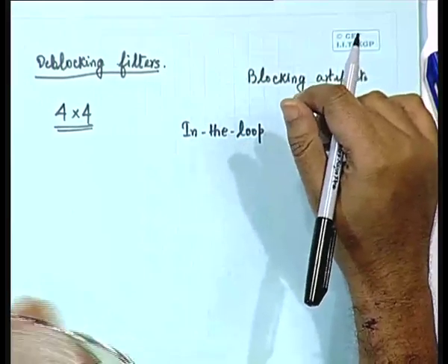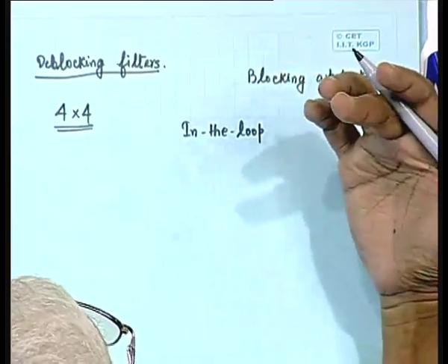What I talk of as encoder loop, I think you understand. Few classes back when I was explaining about the encoder, I have shown you that the encoder has got a forward path for the propagation of the residual coefficient, and also it has got a feedback path in order to derive ultimately the predicted signal.